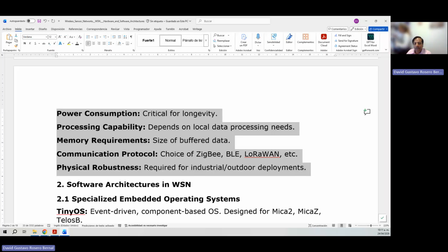For this specific requirement, we need to have adequate buffer size for data storage and program executions without significantly increasing energy consumption. We need to consider as well the communication protocol compatibility, as we need to be careful in matching the radio to the protocol needs. 6LoWPAN for mesh networking, LoRa for long range, low bandwidth communications, BLE for mobile interactions, etc.